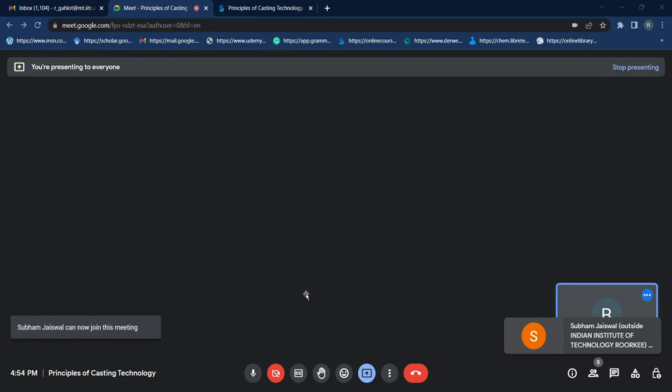Now the third one is the hot tear defect. Why does it happen, the hot tear defect? Sir, I think when the molten metal is in a hot state, it tears some wall. I think some crack is generated in the wall, and that's why the molten metal flows in that. That term is known as hot tear.